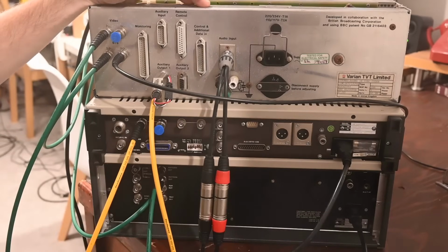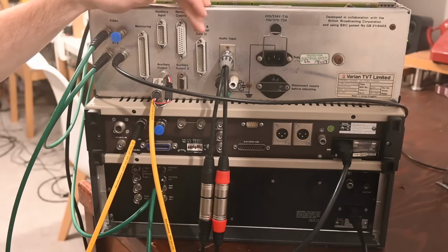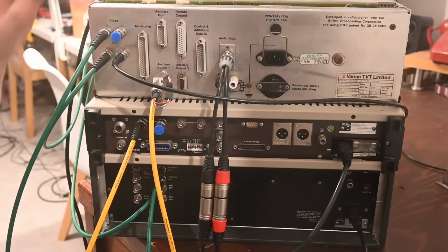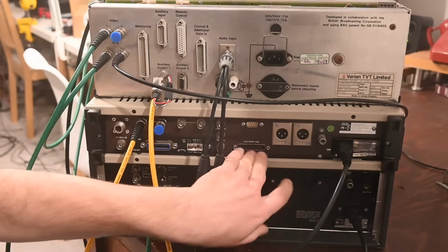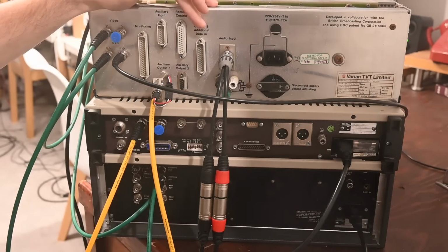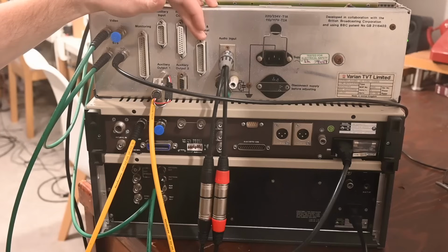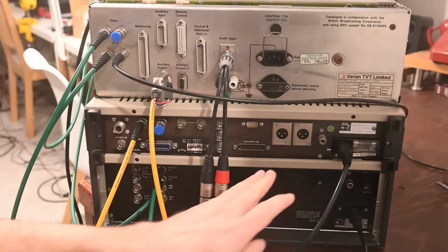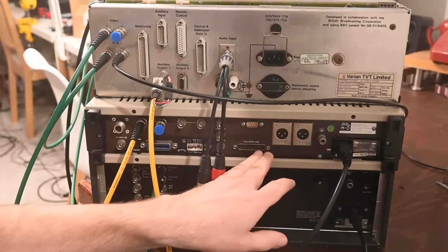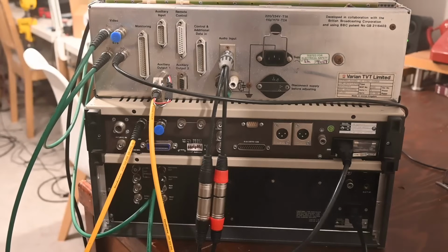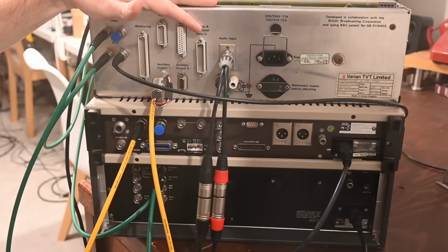So NICAM has a few spare bits where you can stuff extra data into the frames, and it works out to be a few kilobits a second of auxiliary data. And you could feed that into this connector and hypothetically receive it out of that connector if using this particular decoder. And I don't know if this is a standard pinout or if this is proprietary. We know the pinout for the Philips one because we have some documentation for the successor of this, but we have no documentation for this at the moment, obviously.